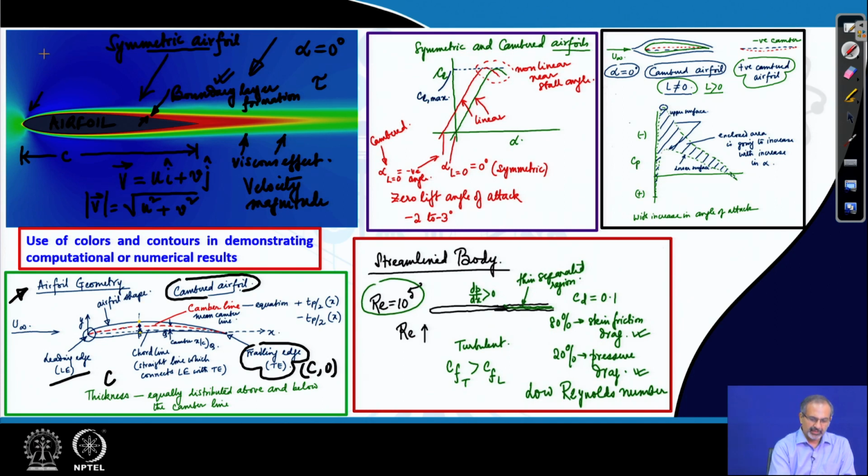Moreover, it seems to be thinner closer to the leading edge of the airfoil, and it thickens as it moves downstream, and the red portion probably has the highest velocity deficit, that is also extending into the wake region of the airfoil. So, these are things that we can cleverly guess from what we can see from the picture.